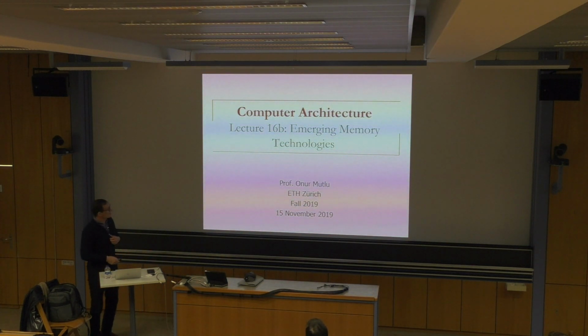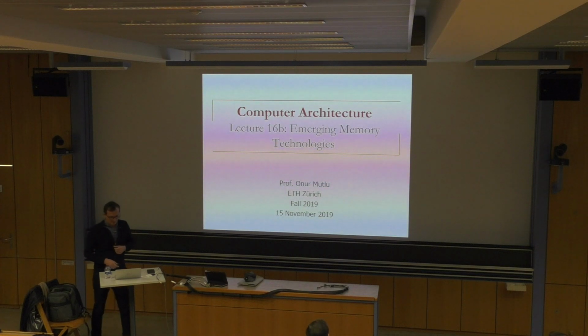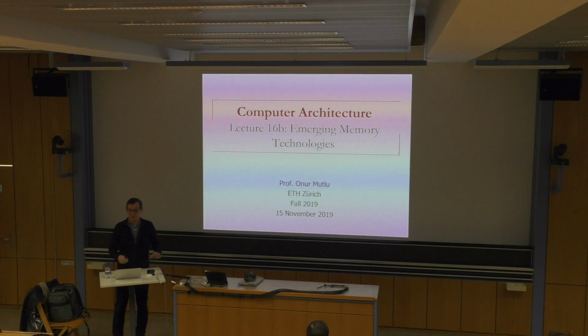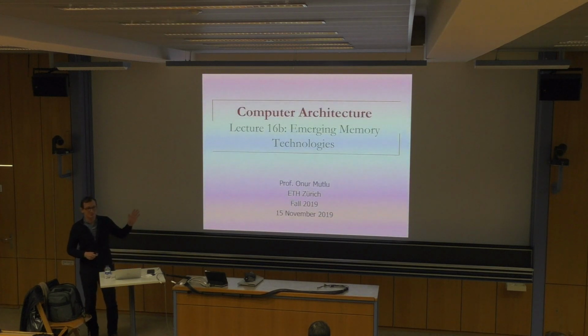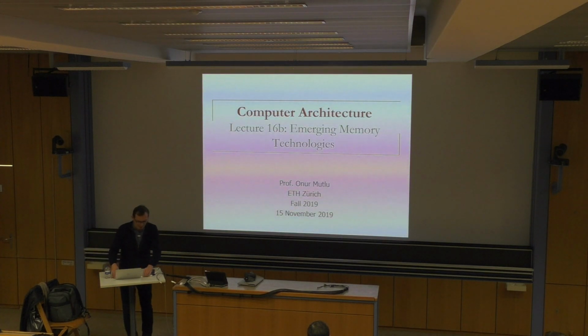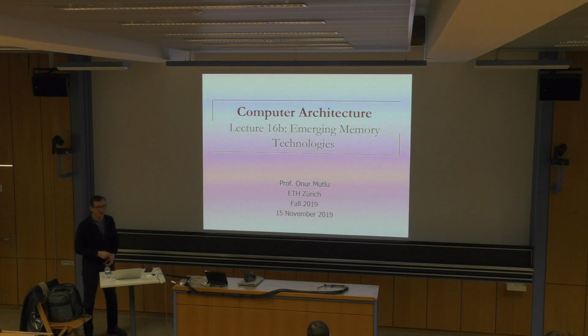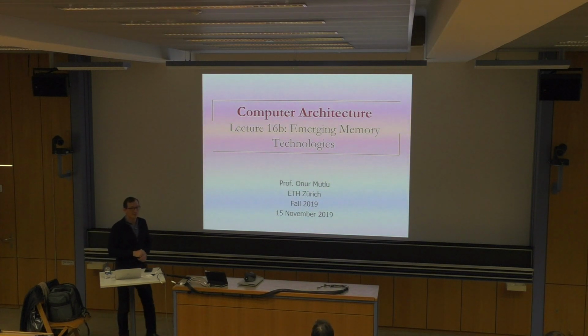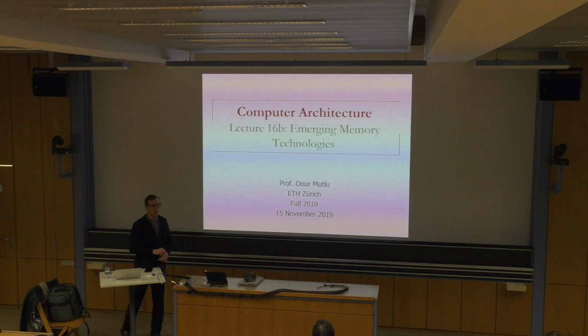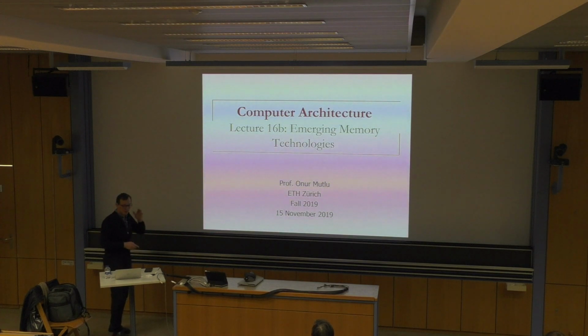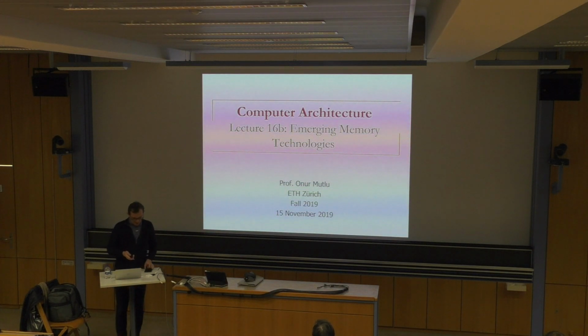Okay, and emerging memory technologies, at least to replace main memory, was a dream even 5 years ago. But today we actually have this. I showed this as one of the exciting things that's happening in computer architecture today in the first lecture, right? Today we have the persistent memory, Optane persistent memory by Intel. You can buy it, you can plug it into your DIMM, and you can use it as persistent memory. But I will give you the story and history of it a little bit.